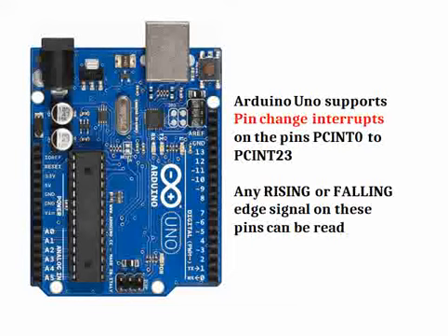In the external interrupt, what happens is once you have the interrupt on a particular pin, that means there is a level change, automatically the firmware gets routed to the specific interrupt service routine and then the instructions get executed. Whereas in the pin change interrupt, it is the firmware engineer who has to write the code to find on which pin it has changed. The firmware engineer has to read and then invoke the respective ISR.